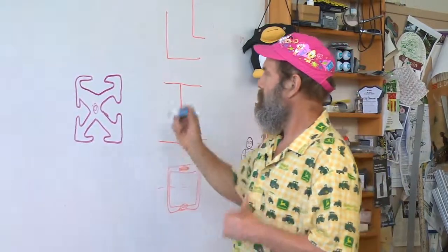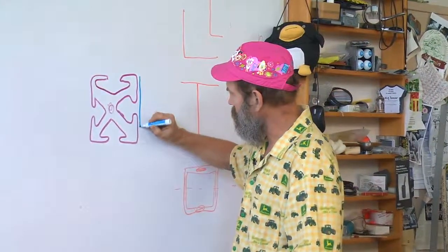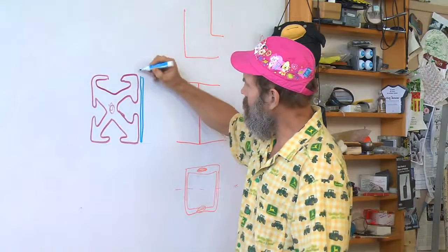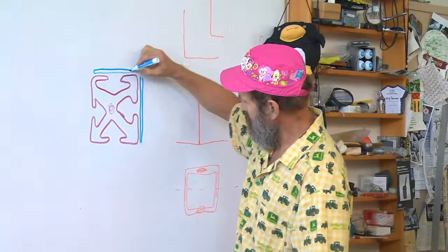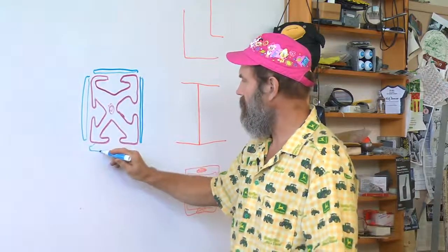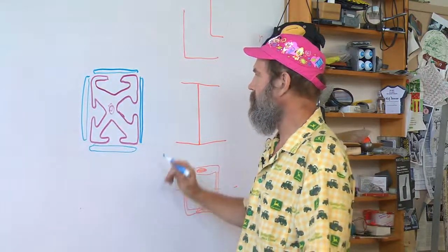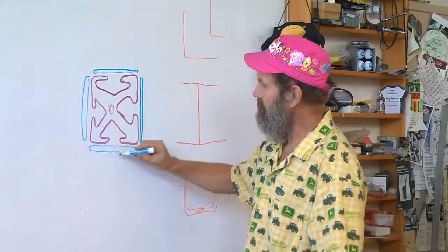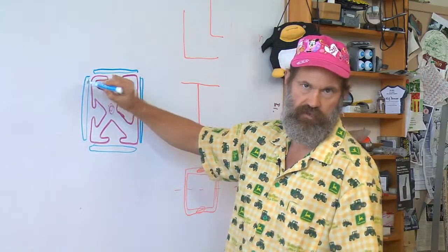So while I've been burbling away, you've probably been thinking, yeah, I've got the answer. I somehow need to close the sides of this. If I could somehow close the sides, I would now have a closed path for the torsional structural loop.